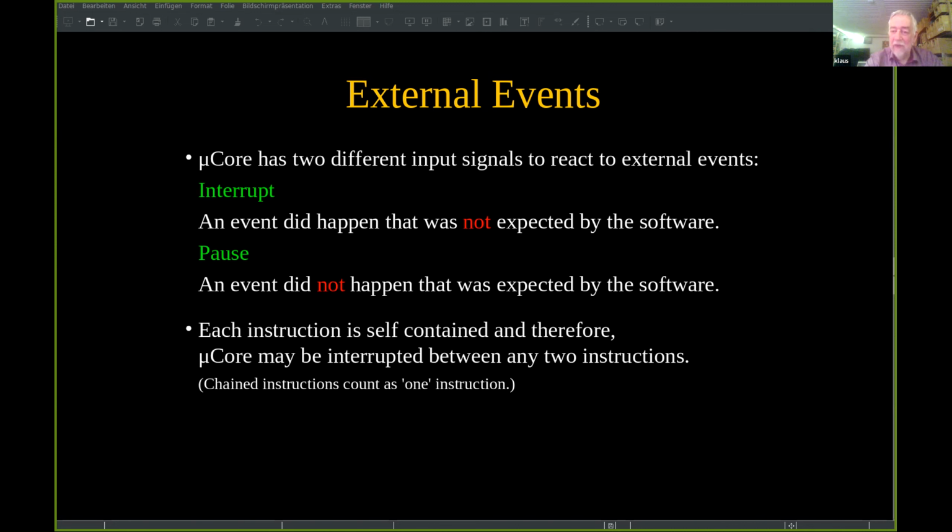If there is no character, then a pause is raised, which in effect leads to a call of the scheduler and running a different task. Eventually you will come back to the task that experienced the pause, and at some point in time the character will have actually arrived and the program can continue. This, by the way, is also something that I inherited from the Transputer, which, to my knowledge, is the first piece of hardware that had such a mechanism.